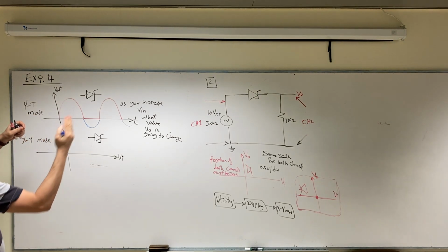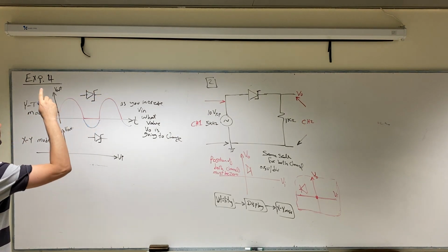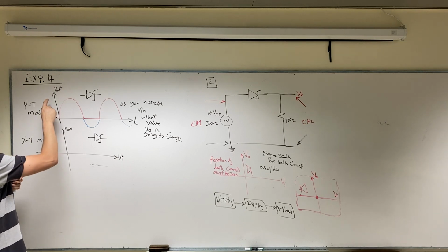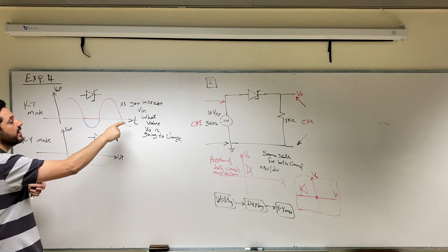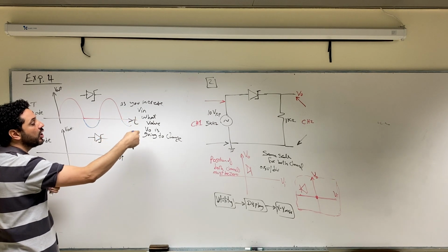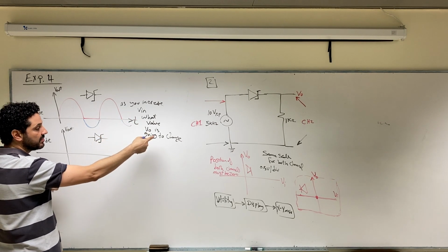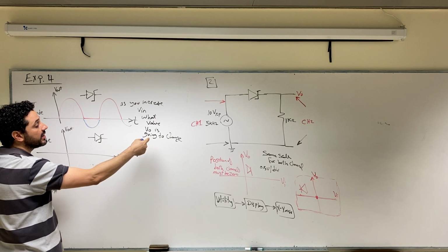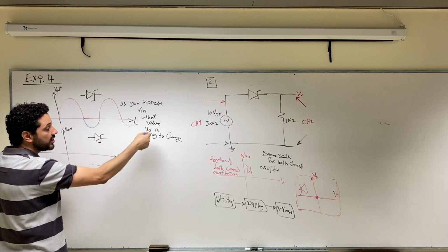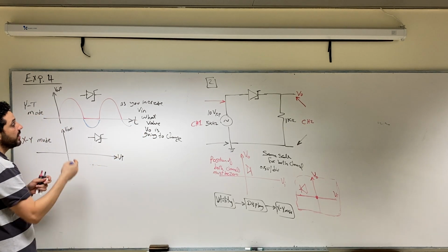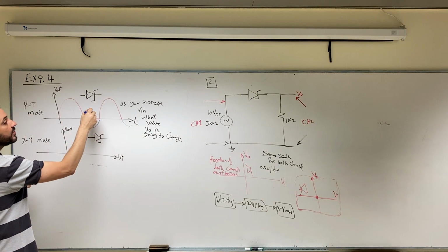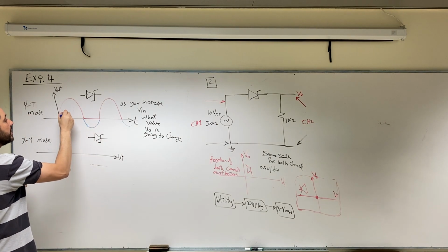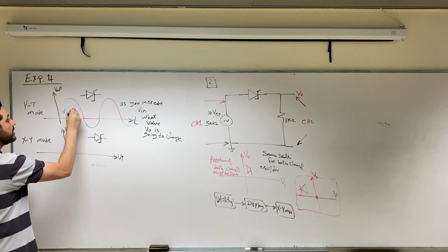So here for the Zener diode in this direction, we are going to plot 2 plots. First plot V output against time, and then you show me as you increase V input, what's the value of V input at which V output is going to change shape. And then you sketch the shape of V output for V input equals 10 volt peak to peak.